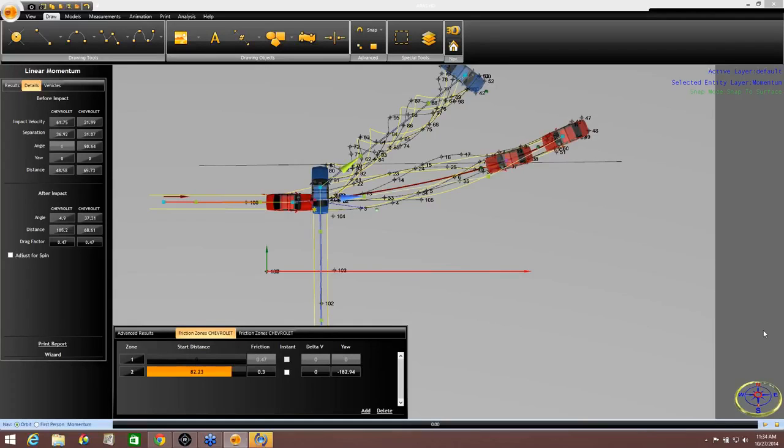Another question. What basis do you use to figure the free drag factor? So rolling friction, I guess, is what you're asking. In this case, we did a test for those cars. We took the cars over a measured distance and got them up to a speed. And then over the measured distance, what was their speed? What did it go down to? And we did a calculation to see what their deceleration rate was, just simply coasting.